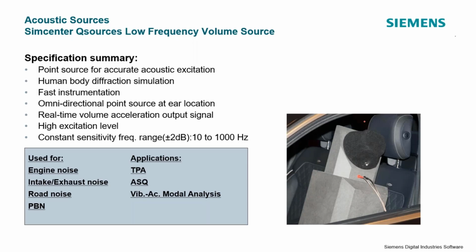I have since done that with this piece of equipment. It's very good at generating not only broadband, but very high amplitude at those very low frequencies. So you can actually measure a response acceleration on a vehicle or other massive structure using an acoustic source in the passenger compartment as your exciter.